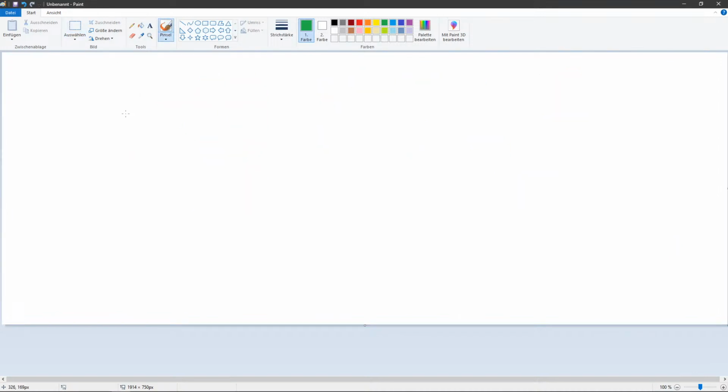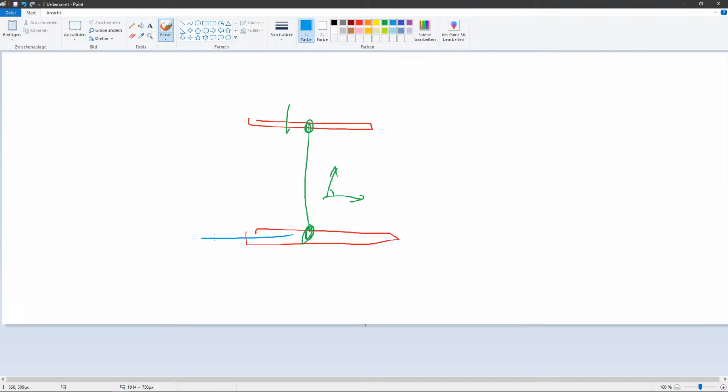So basically what I thought would be possible, if you have this MPC here at the top, and then you have some MPC at the bottom, and between those two you have this 1D bar element. You know the direction. You can also get the perpendicular direction. You get the forces which you sum up from the MPCForces tools here and also here from the RVE.